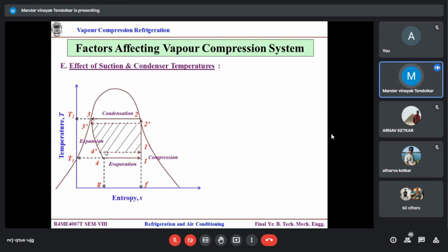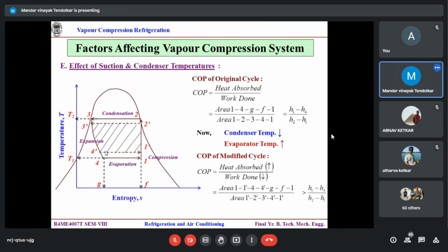I will keep the compressor the same so that input is the same and output increased. So for that, instead of the right hand side compressor, I will try to do something on the left hand side, that is the expansion. That will be the assured technique for the increase in COP. Do you agree? Yes, sir, agree.